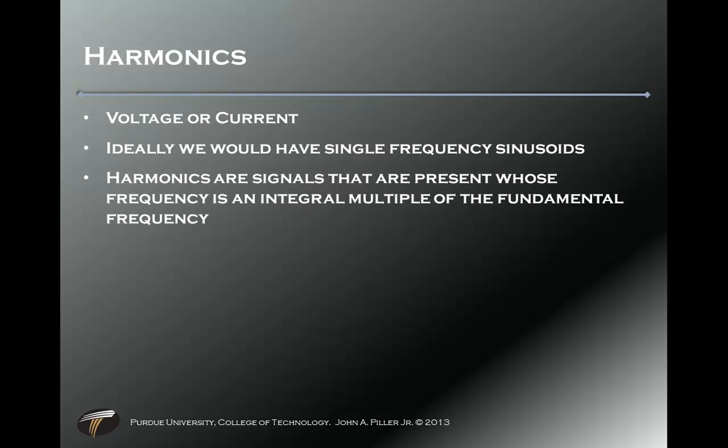with the electronic world that we have today, we are switching power supplies, diodes, rectifying AC to DC, DC to AC systems. We end up creating noise on our line inadvertently to produce those waveforms, and you have multiple frequencies that divide up our actual fundamental signal that we're looking for. Harmonics are the signals whose frequency is an integral multiple of the fundamental frequency.